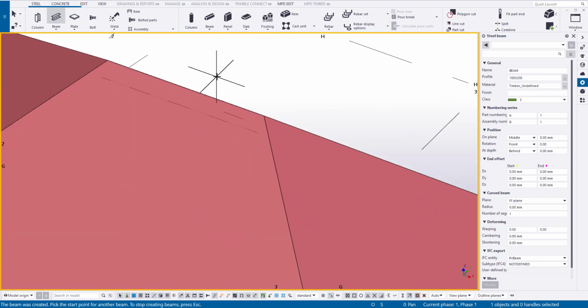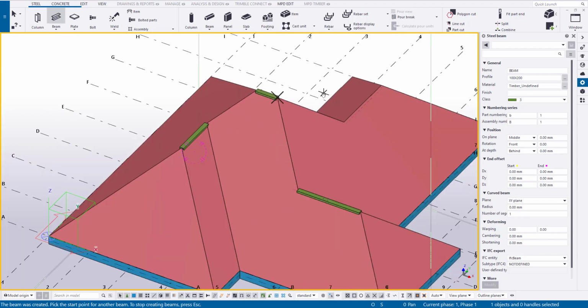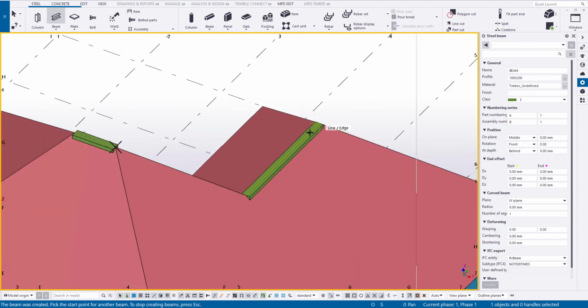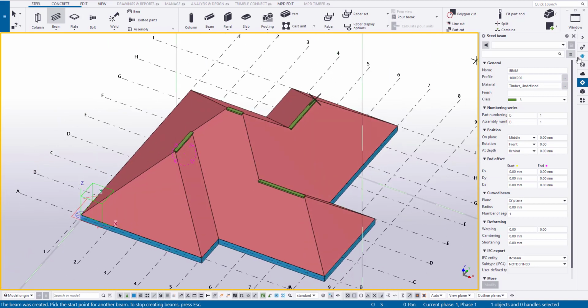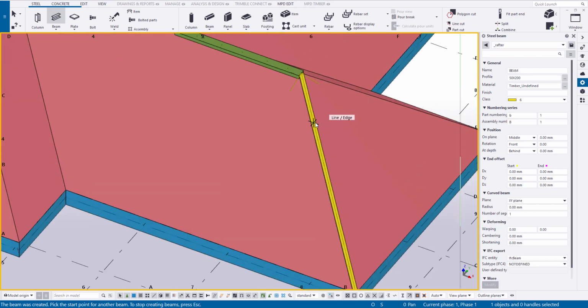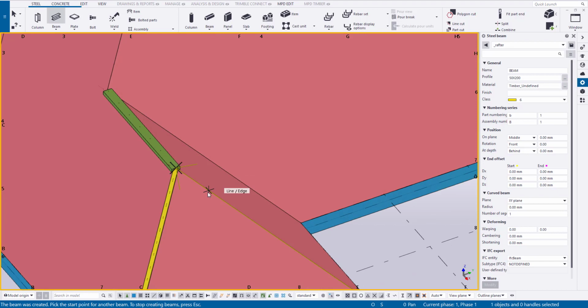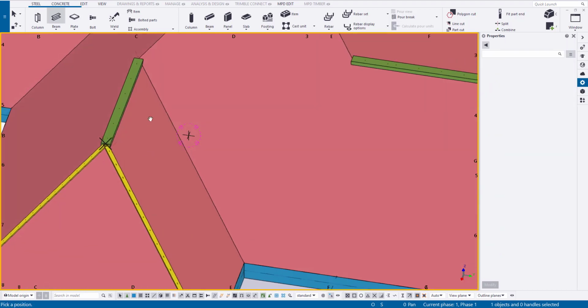In the previous video, I created the geometry of the roof as a reference model. When modeling real structures, I almost always create zero-weight elements, which are not included in the drawings and reports. Next, we will proceed to create ridge and rafter beams based on this auxiliary geometry.